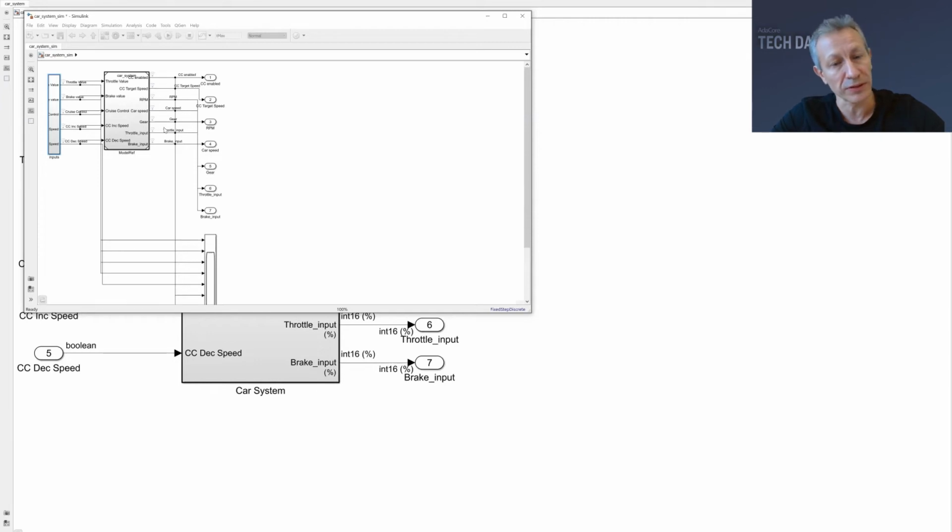And on the output side, we are reading the results produced by the generated code. We are comparing them against the results that we have from simulation so that we can verify whether there is any deviation when you are running your generated code.